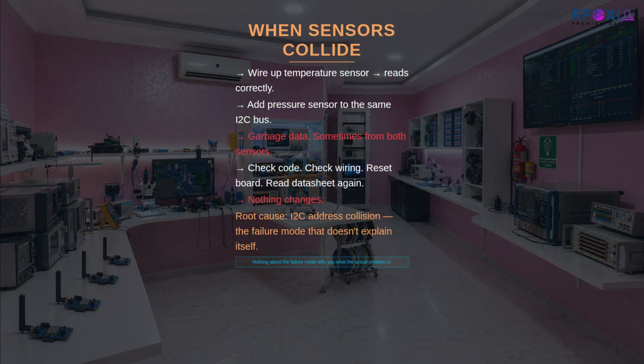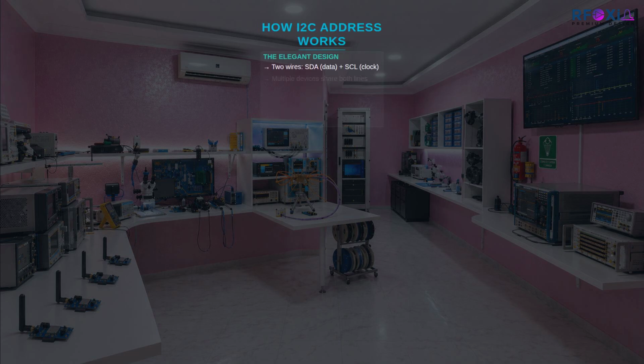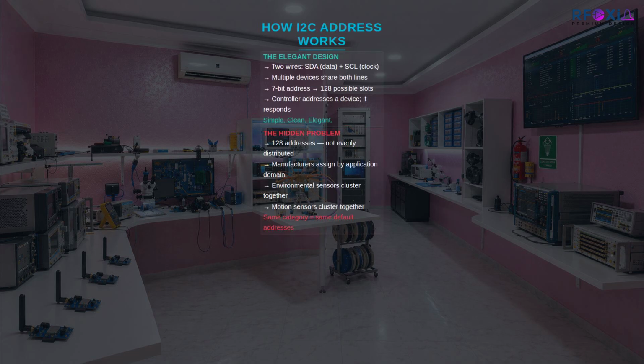And if you have never hit one before, it is a genuinely confusing experience because nothing about the failure mode tells you what the actual problem is. Here is what is happening. I2C is a two-wire communication protocol, one line for data, one line for clock. Multiple devices share both wires and they take turns talking based on a 7-bit address. The controller sends a start condition, puts an address on the bus, and whichever device recognizes that address responds.